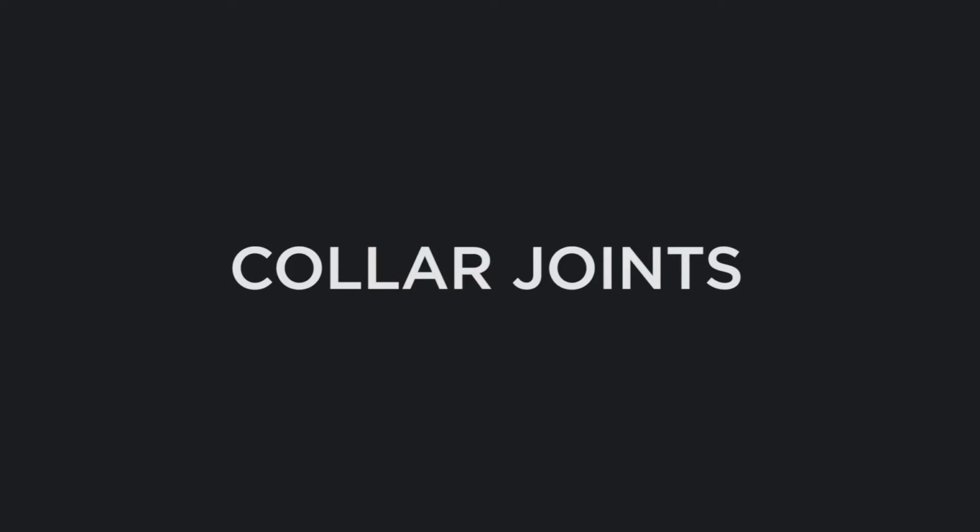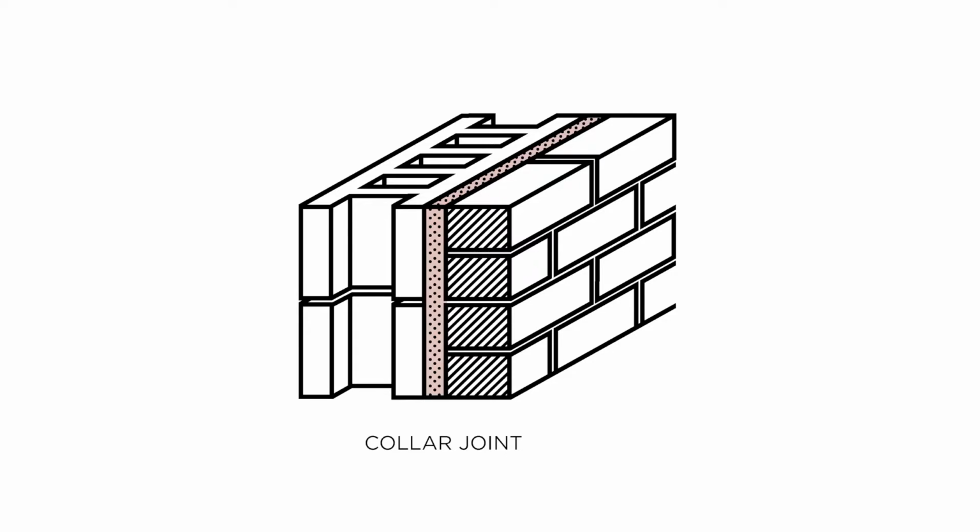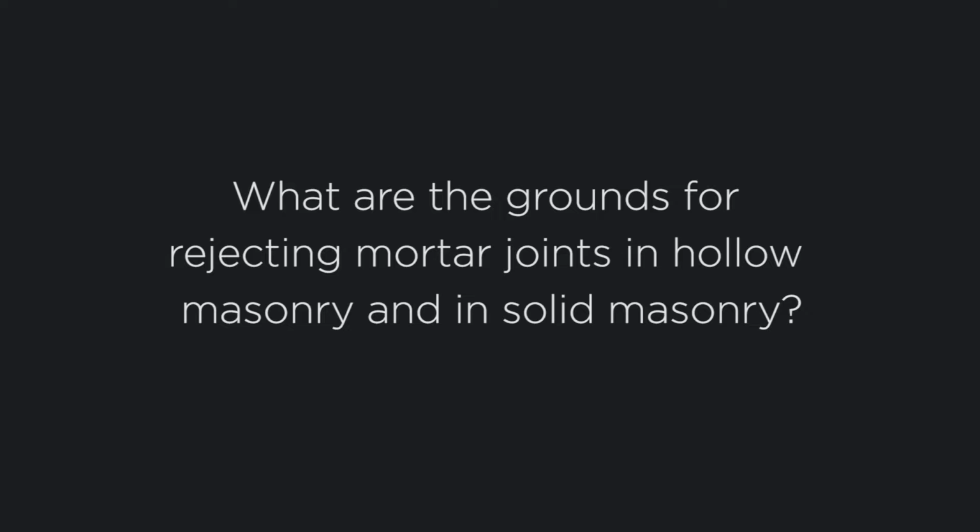Collar joints. Unless otherwise required by the project documents, collar joints less than 3/4 of an inch wide must be filled with mortar as the work progresses. What are the grounds for rejecting mortar joints in hollow masonry and in solid masonry?